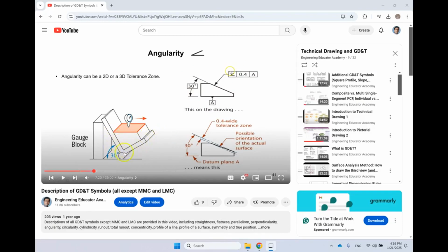And one of the things, if you remember, we had to do this gauge was we had to have a tilting table like this that you can set at a specific angle, so you can put your part on that and tilt your part as much as that angle. Then that surface of interest will be horizontal, so you basically gauge it like you do it for flatness of a horizontal surface.